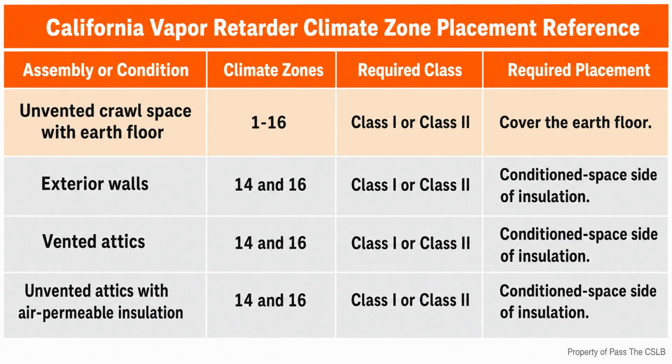The aggregate would sit between the retarder and the slab, so the retarder would not be in direct contact with the concrete. The correct supervision response is to restore the specified layer order before the pour, when the correction is still visible and reachable. This is a useful connection between envelope work and concrete work.